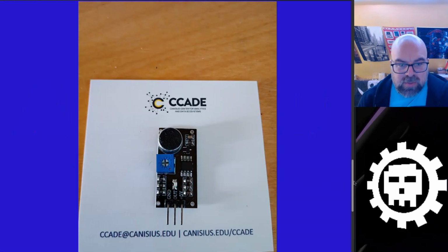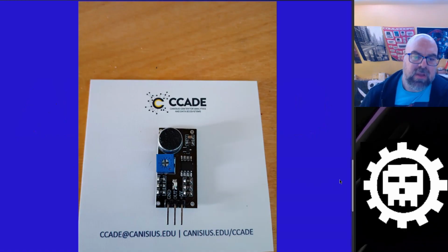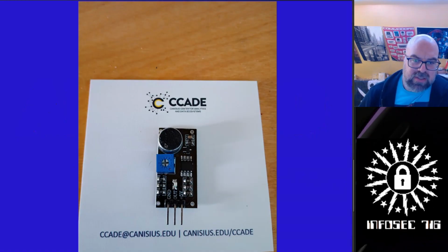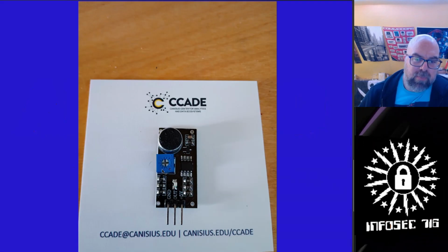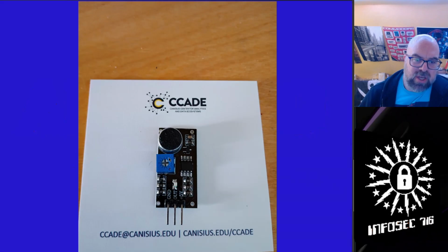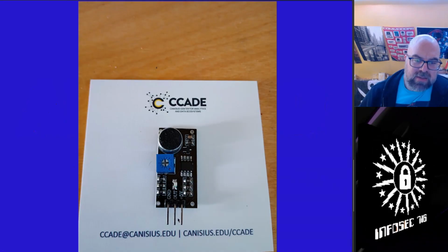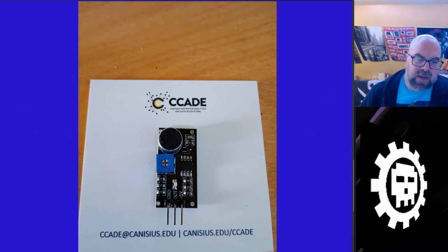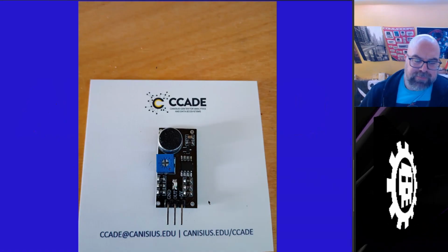You probably remember this picture from last week. This is a digital sound sensor. This black circle here, this is a microphone. This blue box with the adjustment screw in it, this adjusts the sensitivity of the microphone. And then these 3 pins are used to integrate it into our circuit. We've got a ground, we've got a power, and then we have an output pin.